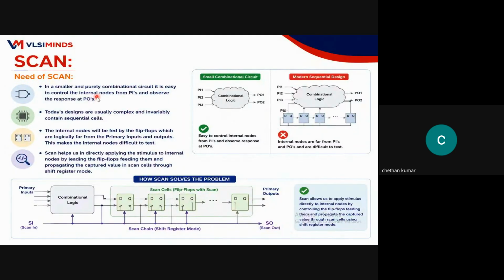Nowadays, as you all know, chip complexity keeps increasing as we move towards lower technology nodes. Internal nodes are fed by a lot of flip-flops which are logically far from our primary inputs, so we cannot access these pins directly from the primary inputs. So to solve these problems, all these flip-flops will be sequentially connected.